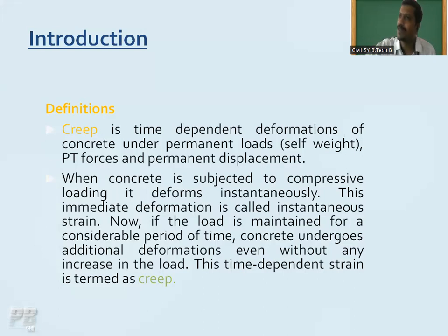So on the same platform, our concrete structures are also being exposed to deformation. What is deformation? It is nothing but the dismantling or deterioration of the structure. How is it going to happen? It is going to happen with respect to the age and with respect to the load which is acting on it. It may be the self load, any live load, wind load, any type of loading. So there is a continuous load acting on your concrete structure, and due to this, there is a deformation of that particular concrete structure with respect to time, and that deformation you call creep.